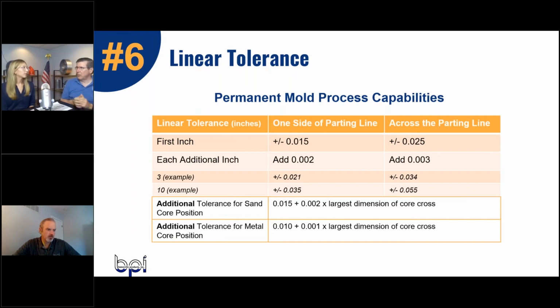Okay. Now, a core would create a hollow spot inside the casting, and those cores are tied to either the top, either the cope or the drag, the top or the bottom of the mold. All right, and they have cores for sand and for metal that vary. We use metal cores and we use sand cores, and when the sand cores are used, it's called semi-permanent mold because there's a sand core being used. Yes. Yeah. All right.